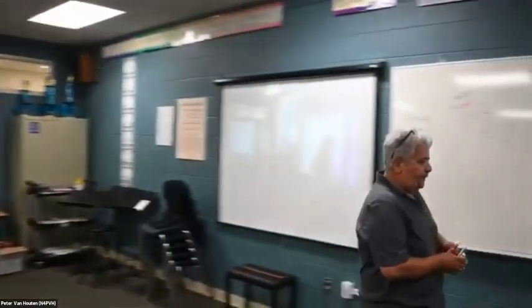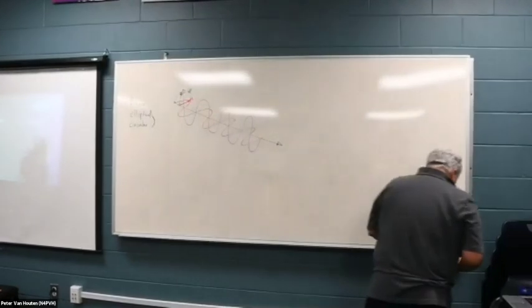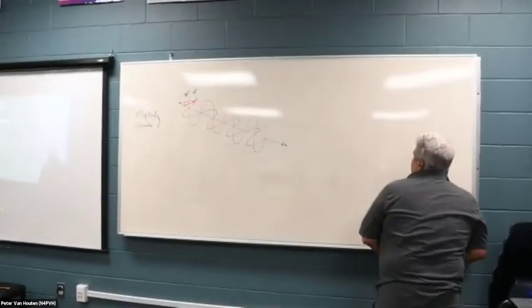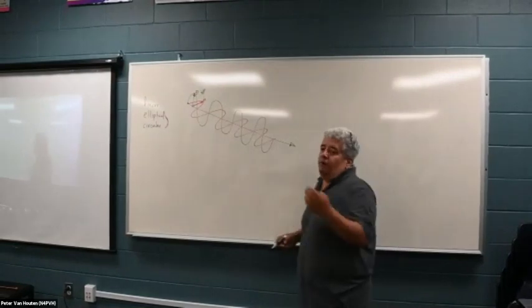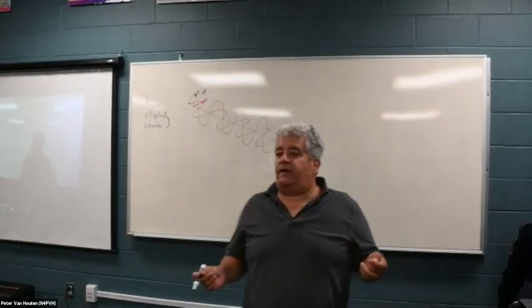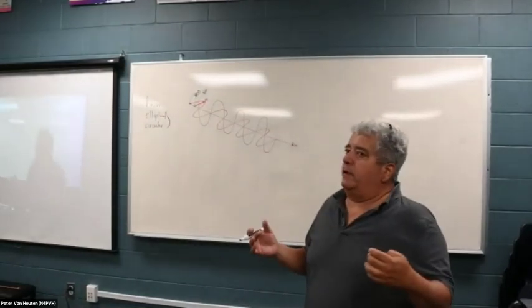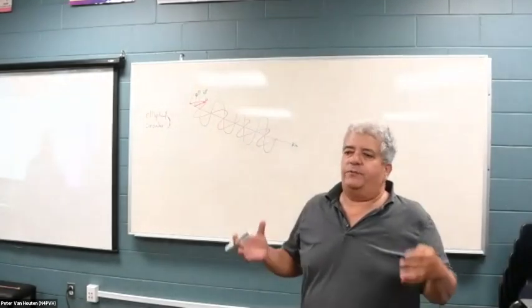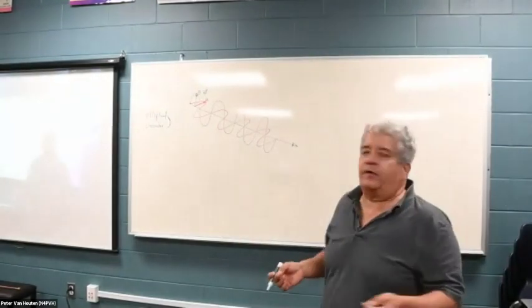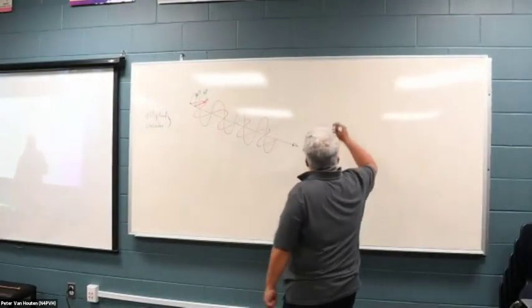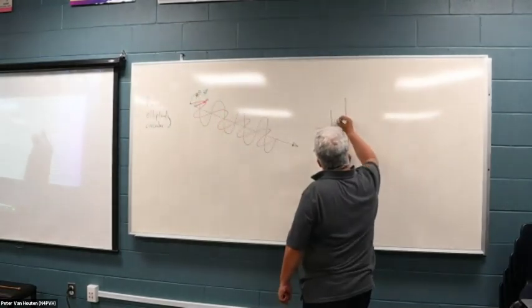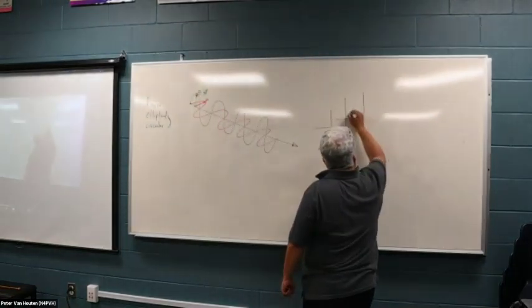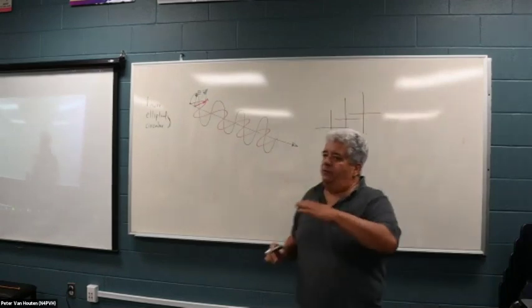Then, going back to the antennas thing, now that we know that, there are several ways to achieve circular polarization or elliptical polarization, which is pretty close to circular polarization. Okay? One method is having Yagis that are put on the same boom.